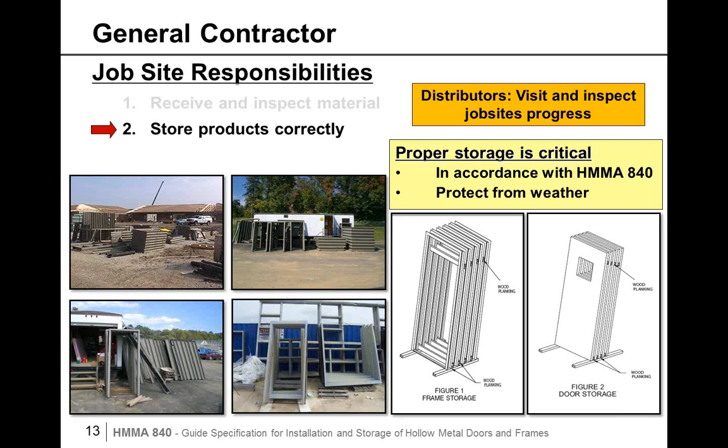This type of storage really relates to back charges later in the job site, and the contractor will usually use the crutch of poor paint or defects in the paint, etc. But the key is, in visiting job sites, if you see anything like that going on, take a picture and store it with your phone or any kind of camera, and just keep it for future protection and offsetting of any type of back charges.